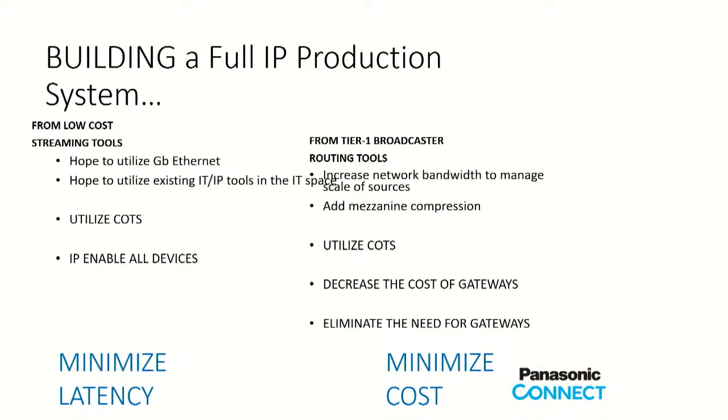And latency was the biggest challenge in the IP world, because in order to transmit, they have to compress, and in order to view, they have to uncompress. Now you're adding latency on both sides, and that was the biggest challenge. ST2110 tried to address that challenge by putting uncompressed video from end to end.